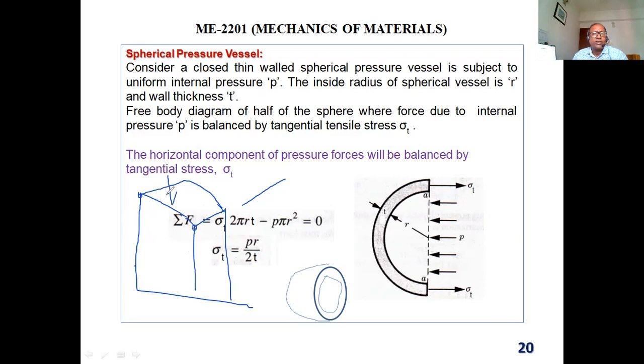The force of atmospheric pressure working at the top, I'll figure out that force. Which area will you take? Pressure, you know. If we calculate the area and multiply by the pressure, you will get the force. So my question: which area will you take? You have to take the area as you see it from the top, then the area will be a rectangle. That is called the projected area. You have to take this area.